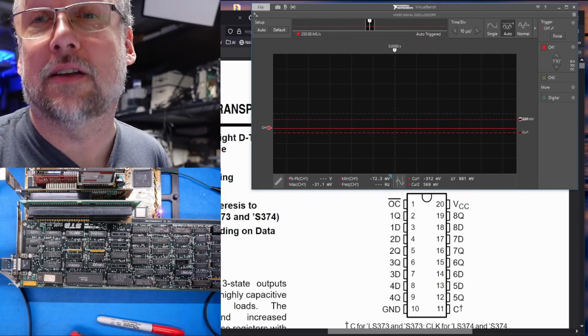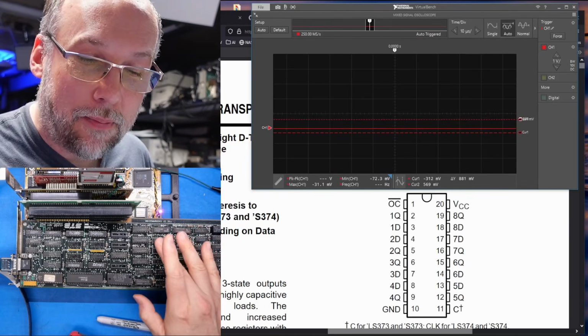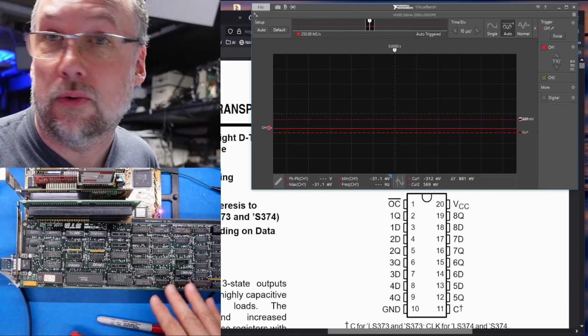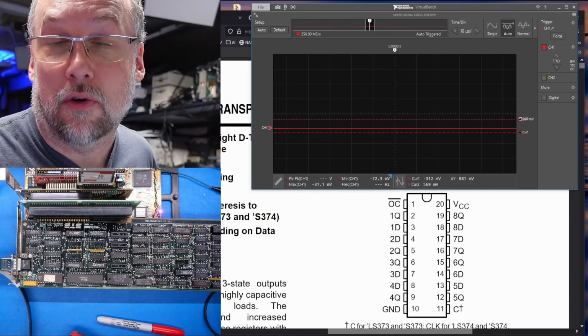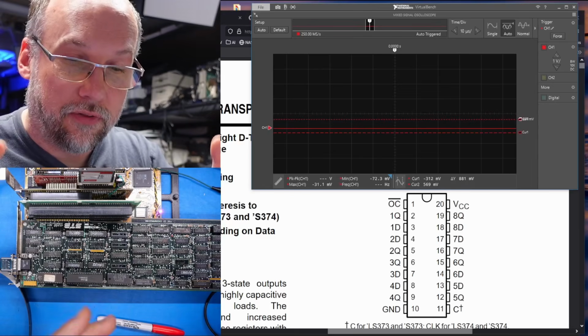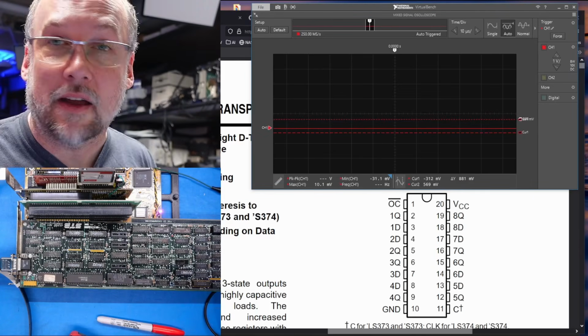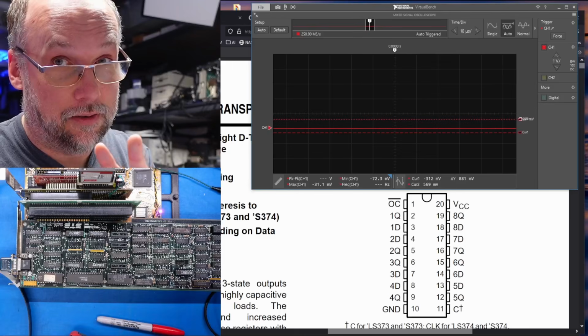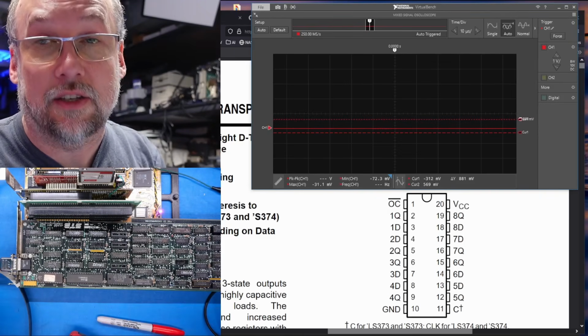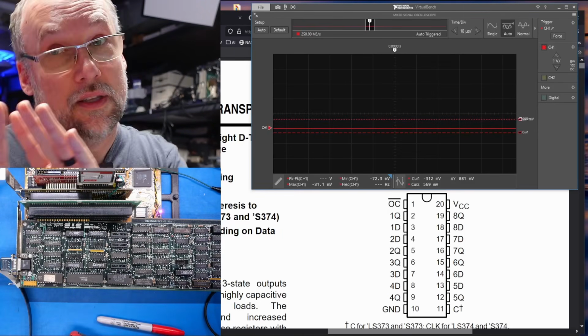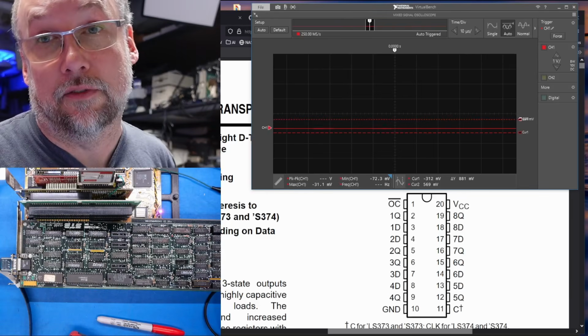And it quite possibly could be that. It might be that whatever chip it's going into has that particular pin shorted to ground. And this is where schematics would be very helpful to figure out where that pin is going exactly. So I'm just gonna do a quick jump cut where I spend a moment to try to figure out where that trace is going on the board to see what the next chip down the line is, because that could be the fault as well.